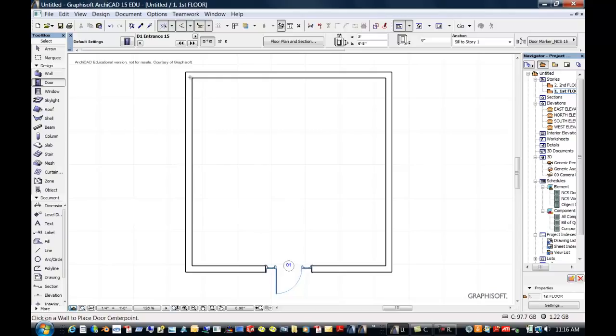So if I come up here and I align without picking with that corner, I know I'm aligned with that because I have my check mark, and I want to put a door so far down on this particular wall, my exit door, and I don't want it to be in the middle, so I'm going to look at this check, then I'm going to type in X, and let's say I want the middle point to be 6 feet 6 inches down this wall. I can do 6-6, and that would be 6 feet 6 inches on my coordinate.